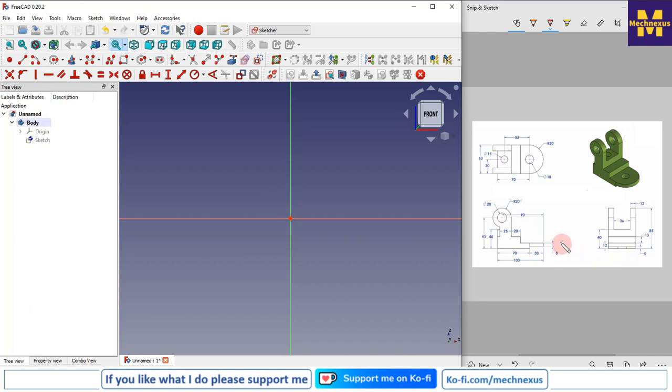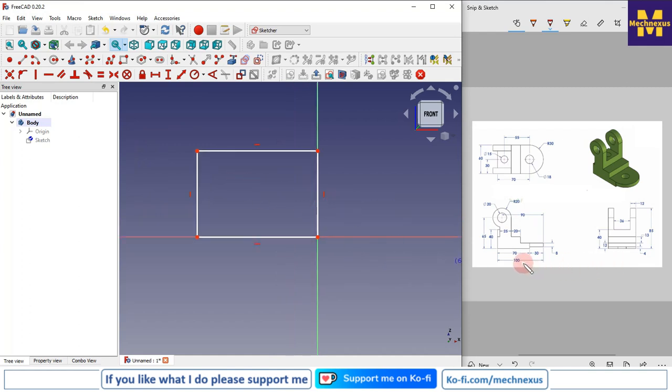Now first we will make a rectangular boss by finding the dimensions. So it is 100 by 85, right? So we will keep our origin here. I will simply select a rectangle and draw a rectangle. So maximum area is here, height is 85.